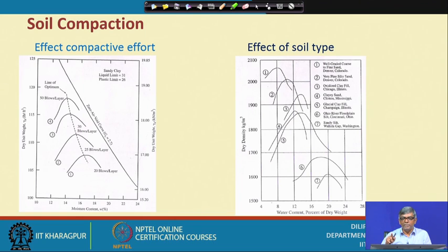Another thing is, if I change the energy for the same soil, the optimum moisture content and dry density will also change. That is explained through these two figures here.